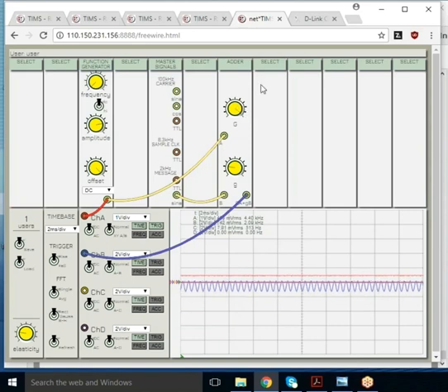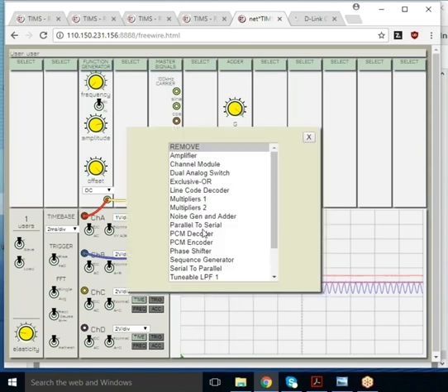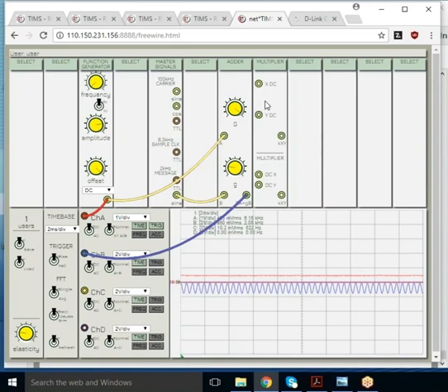So now I'm about to do amplitude modulation. So now I'll put down a multiplier. We have 4 multipliers. So I'm going to multiply that message with a carrier, 100 kilohertz carrier, and I'll look at that on the D channel.